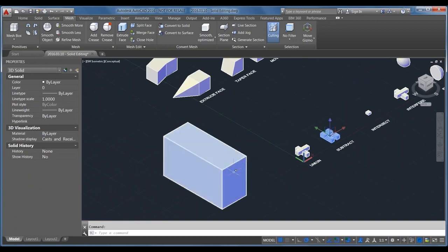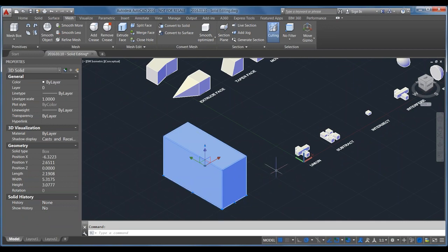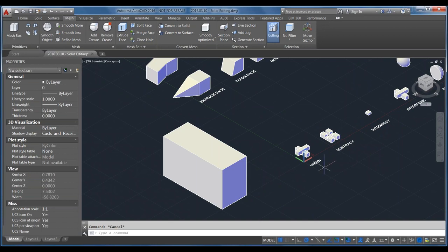Every box will have 6 faces that make it up, and they all have those properties in common, so you can change the height and the width, and AutoCAD knows exactly what to do with that. Once you start changing it into a unique shape, you lose the ability to use those grips because it's unique and doesn't share properties with every other box or every other sphere.